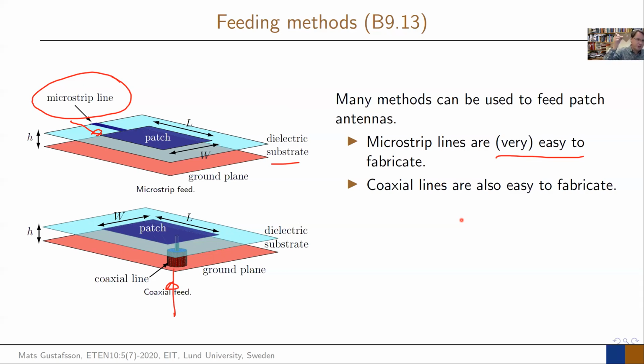This is the patch antenna you will build. And here is the connector to that one, and then it's sticking up. So the exterior connector goes to the ground plane, and the inner connector sticks up here and reaches the patch somewhere. So you have some feed point sitting somewhere here, which is where this comes up to the patch.